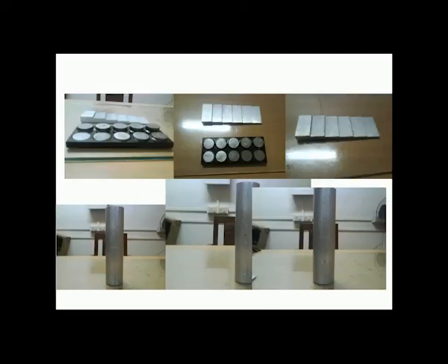Similarly, here also these blocks have different heights or different thicknesses. So, this also can be used to calibrate the instrument for the distance, because then for each of these you can collect the back wall signal itself, and that can be used to calibrate the instrument for distance.